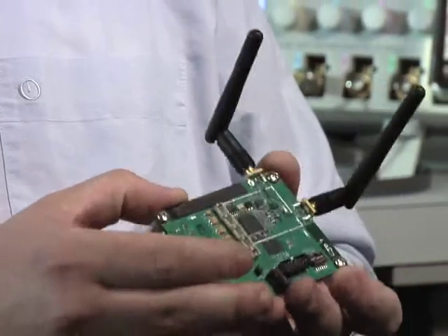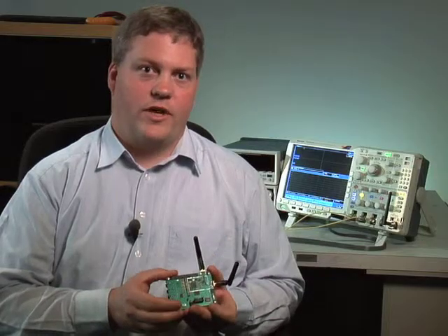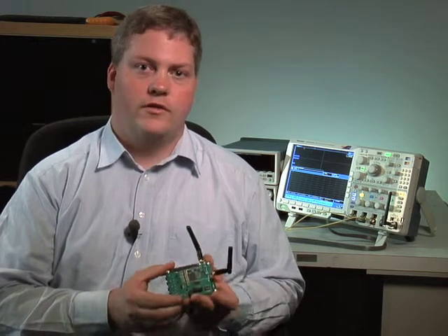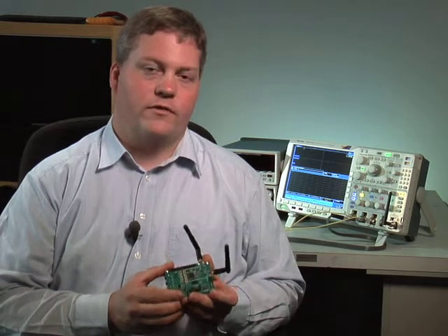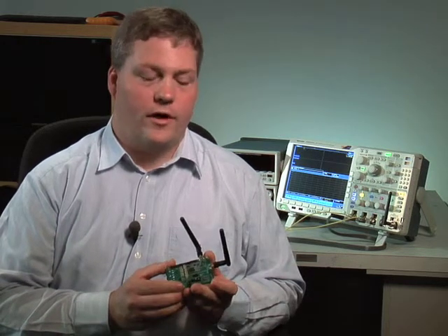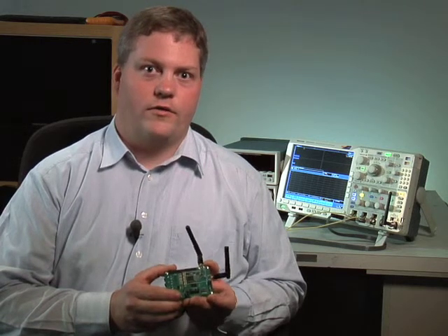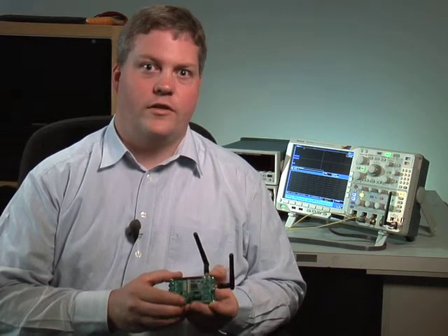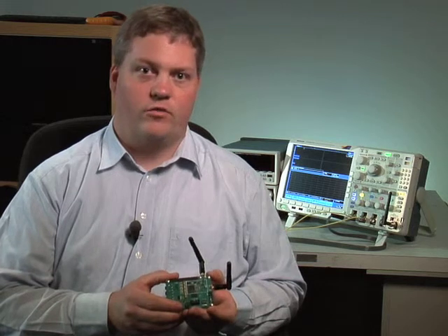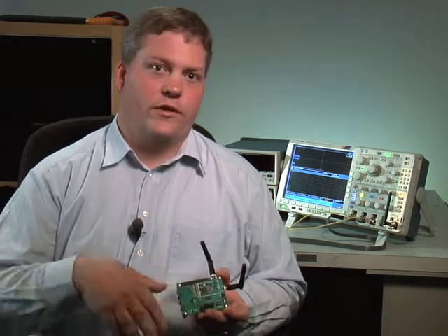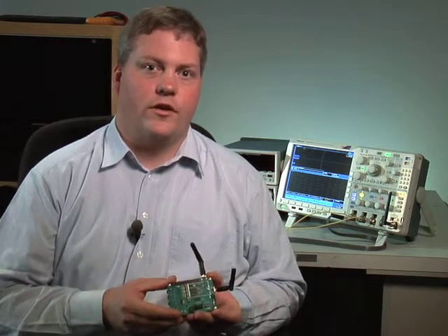And what we're going to look at with the MDO4000 is a number of different aspects of system operation simultaneously. We're going to look at the analog audio, digital audio, serial peripheral interface, and also the RF performance of the IC. And the scenario that I'm going to show is a frequency change command, where I've commanded the system to change frequency via the serial peripheral interface. I'll trigger on that and show the other aspects of system operation and show that they're uninterrupted.